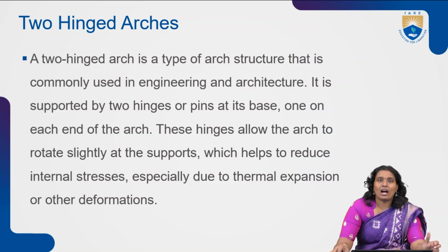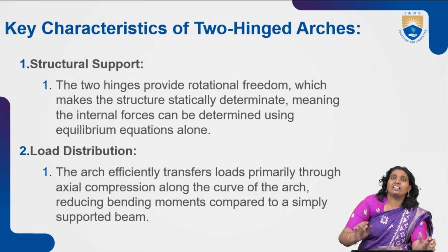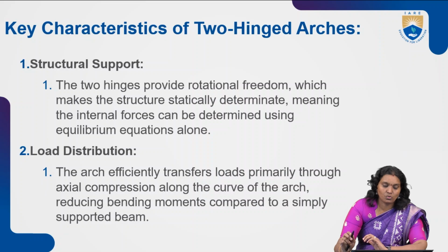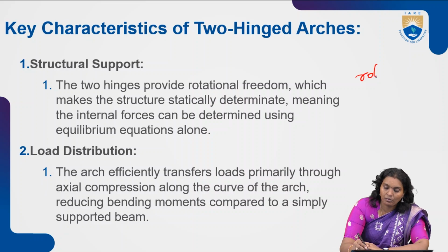It is a type of arch, and it has two supports by two hinges or pins at its base, one on each end. These hinges allow the arch to rotate slightly at the supports, which helps to reduce the internal stresses, especially due to thermal expansion or other deformation. As a key characteristic, these two hinges provide rotational freedom to the structure,